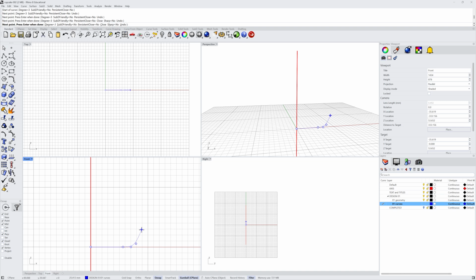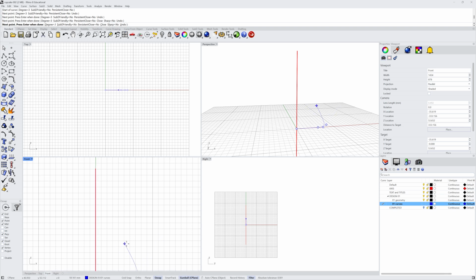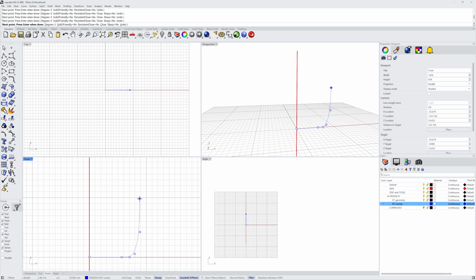And this is the important key as you make revolves. You want to hit that axis perpendicular. So the first two and last 2 points should come straight in. And I'll show you how to do that. So I'm going to come up here. Classic cupcake profile. All right, so if we have the perpendicular O-snap on, that will help us guide it in.